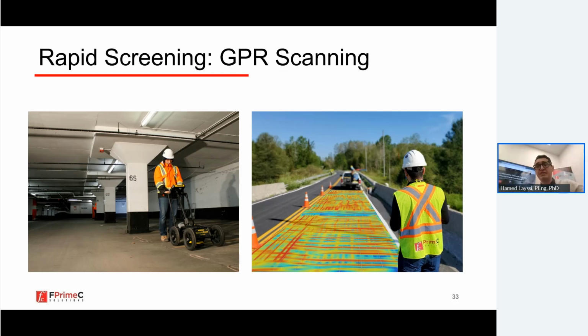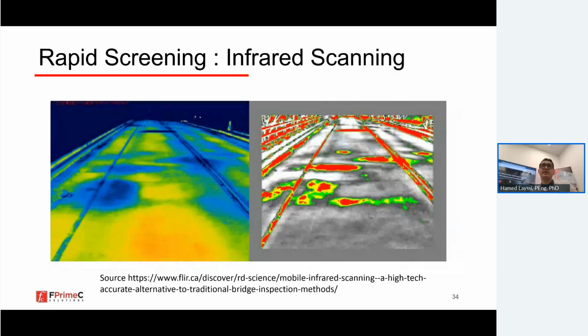So dealing with large areas, GPR scanning and infrared scanning are market standard in the assessment of concrete bridges. They provide very good introductory information: which parts of this concrete slab I need to put my investigation money on and my repair money on.